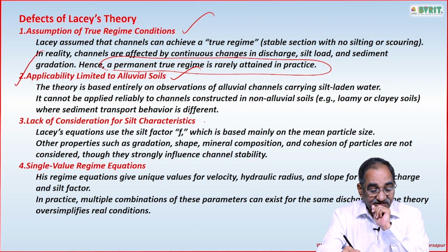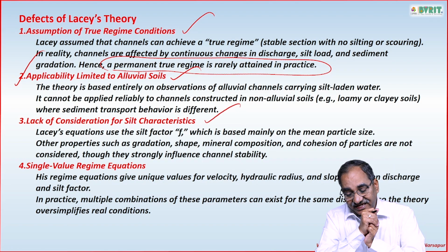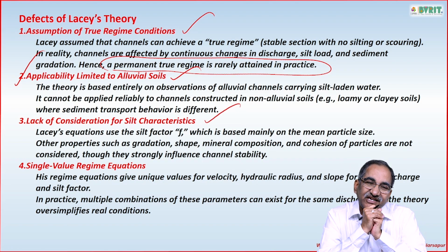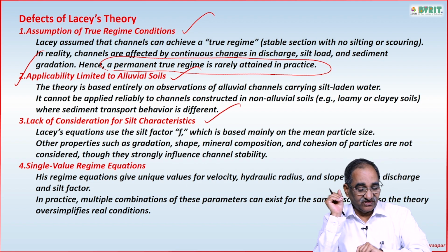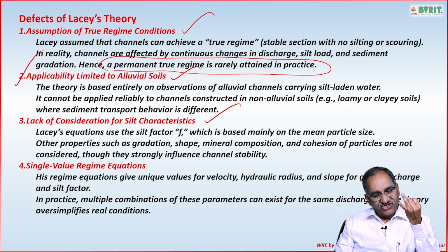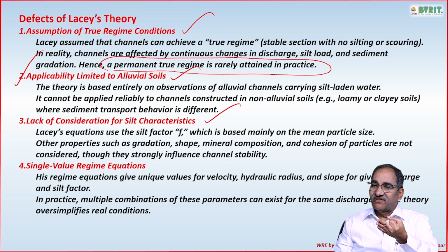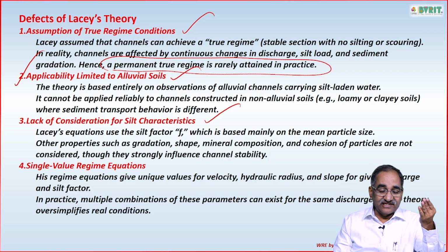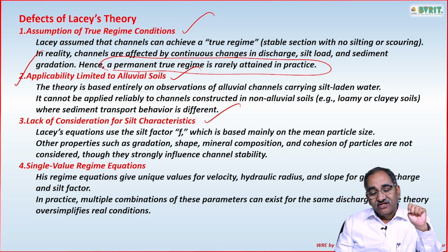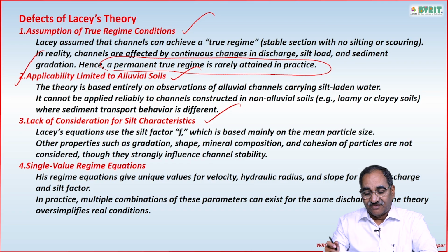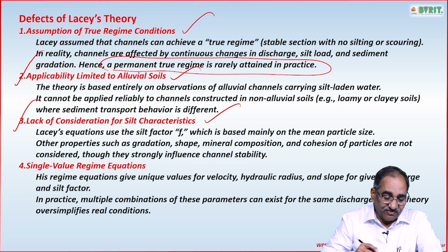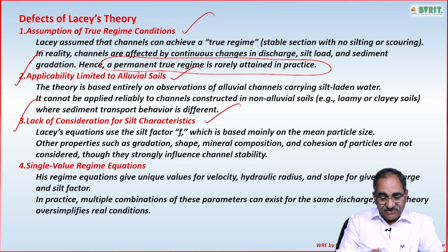Then third one is lack of consideration of silt characteristics. The whole silt characteristic he has considered depending upon the size of the particle actually. But shape of the particle, composition of the particle, the cohesion of the particles are not considered, though they are also going to influence the channel stability. That is the third point. Single value regime equations.